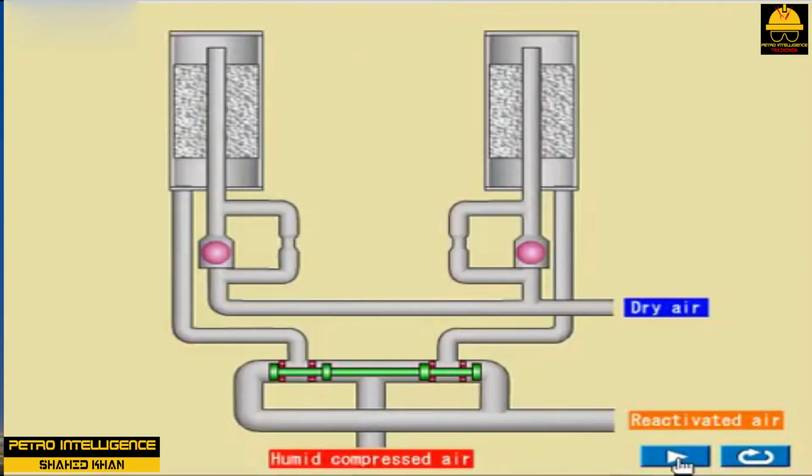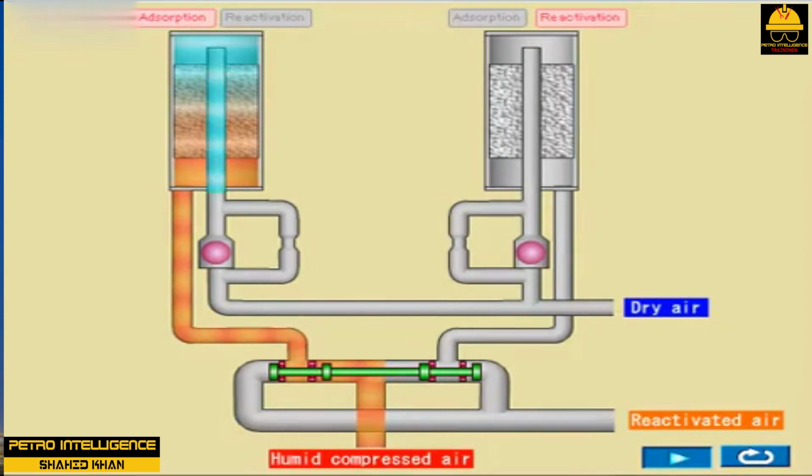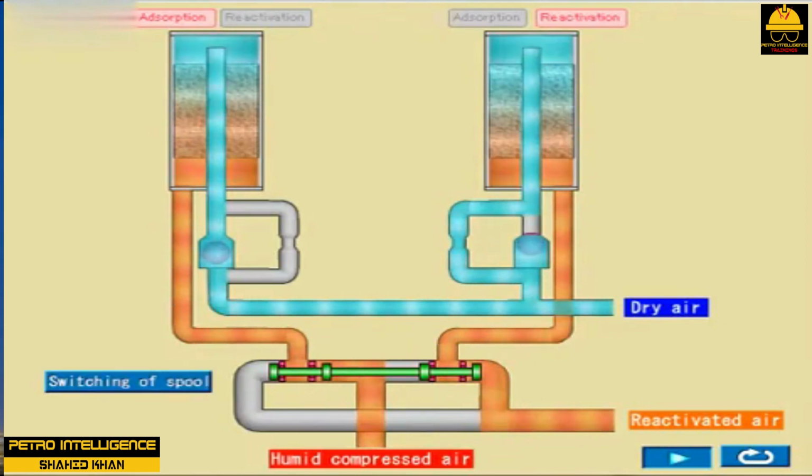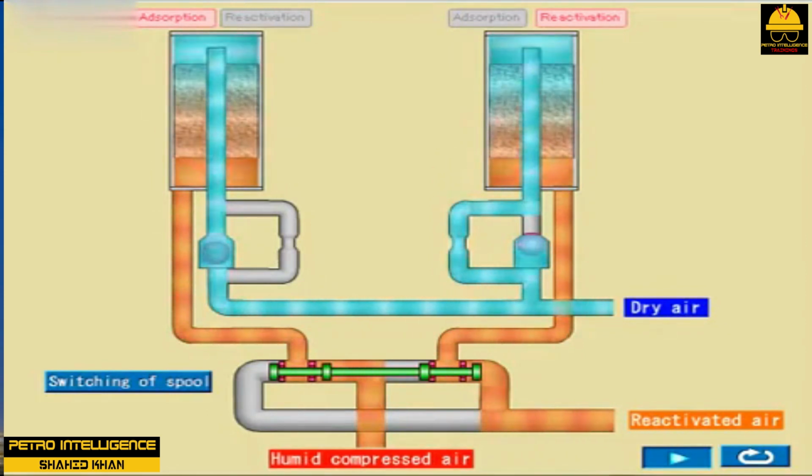A regenerating gas dryer usually consists of two vessels, or beds, containing a granular solid. The solid is specifically chosen for its high adsorbency of the target vapor and ease of regeneration. Piping and valves connect these beds such that the gas being dried enters only one bed. The solids in the other bed are separated from the process so that they can be regenerated. When the first bed becomes saturated, it is switched off the line, the second, regenerated bed is put on the line, and the first bed is regenerated.